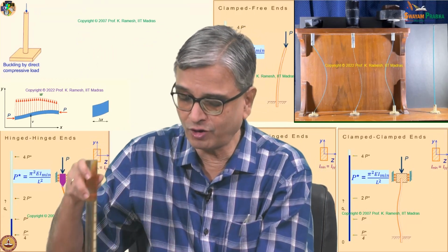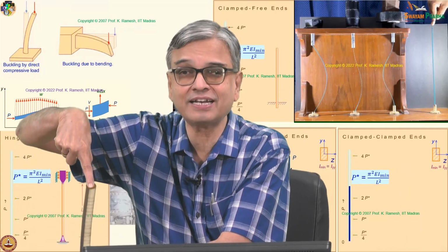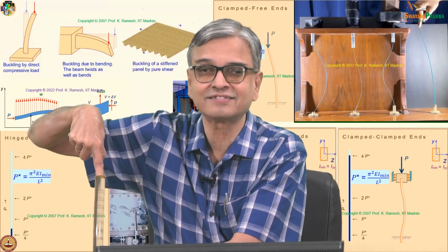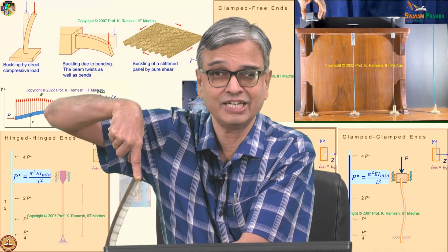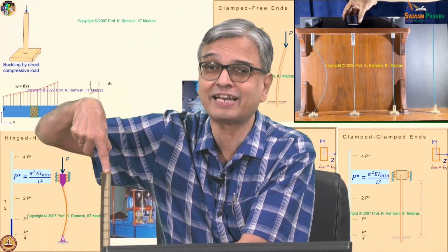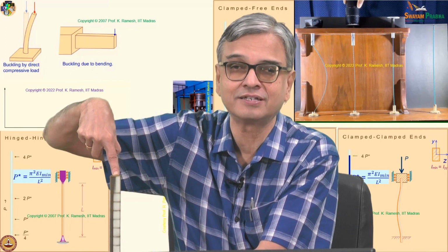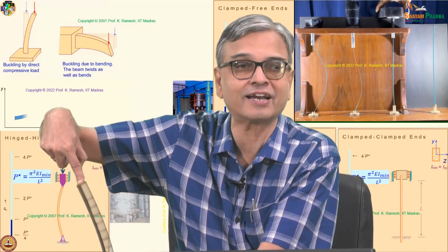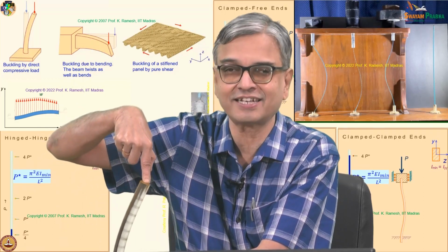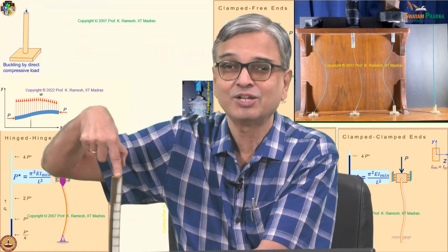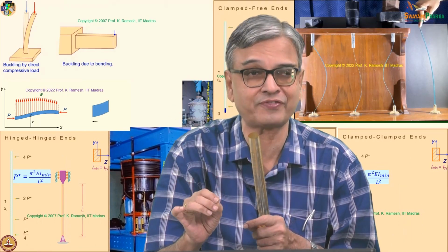So, the probability for buckling to happen can be in any direction. It can buckle like this, it can buckle like this, it can buckle like this. Please understand that. Some of these concepts do not come out very clearly when you read a book, because the book publisher wants to minimize the pages. So, the author can show only buckling in one direction. If you have seen buckling to the right or left, whichever way you look at it, I see it as left, you see it as right. You will think buckling always happens in one direction. No, it is dictated by the moment of inertia.